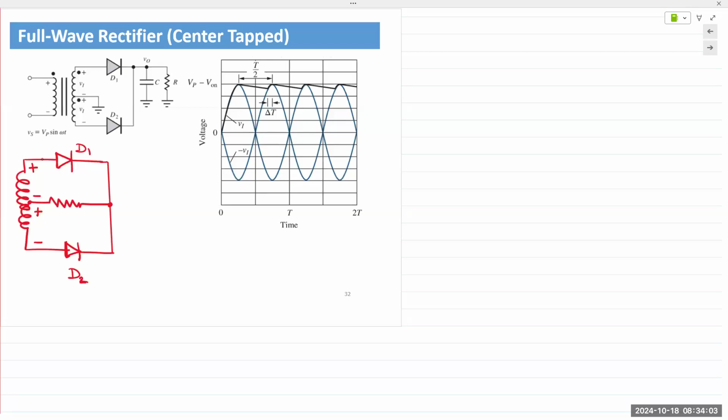So it was not exactly center tap. Center tap, by its very definition, means you're tapping into the center of the secondary coil, so you have equal voltage in both halves. But in real life, depending on your use case scenario, you would be tapping differently. The whole point is that the turns ratio should be different.